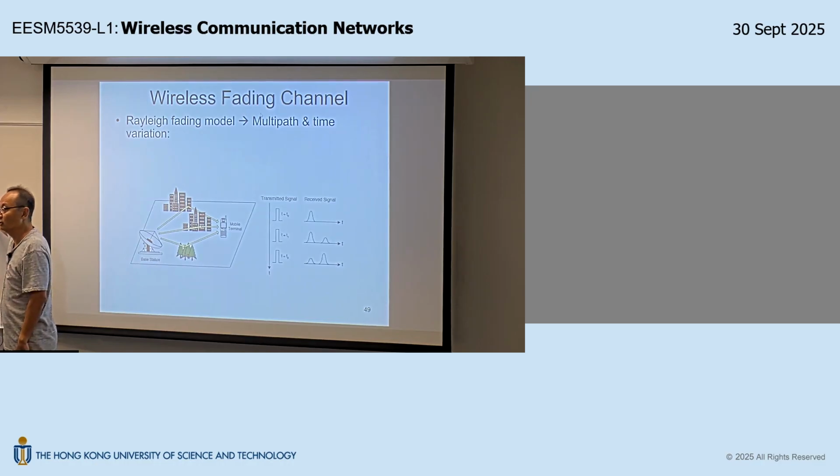Is that okay? So this is one reason that explains why you expect the receive power at your mobile to fluctuate as you move around. Because as you move around, your distance separation from the transmitter changes, right? And when your distance separation changes, according to path loss, your receive power also changes, right? So that's one reason that explains these fluctuations of receive power. Is that okay? Now, some further discussion on path loss.